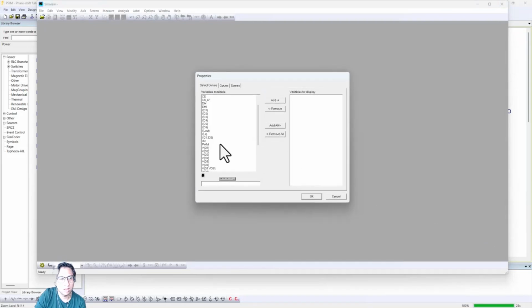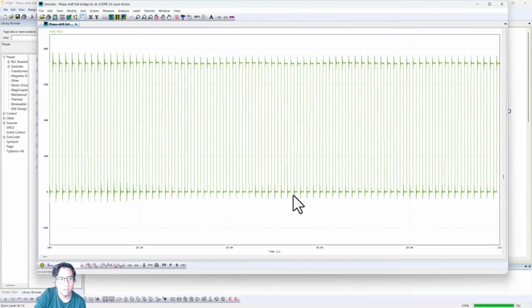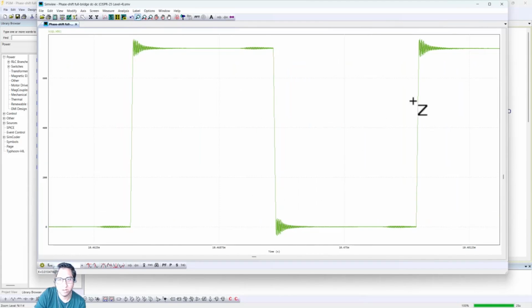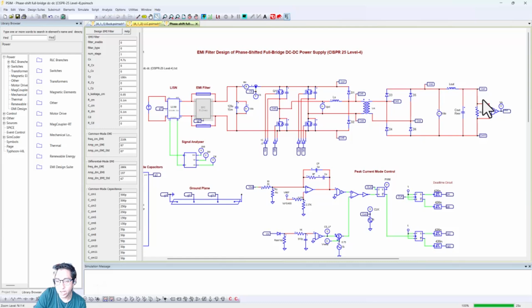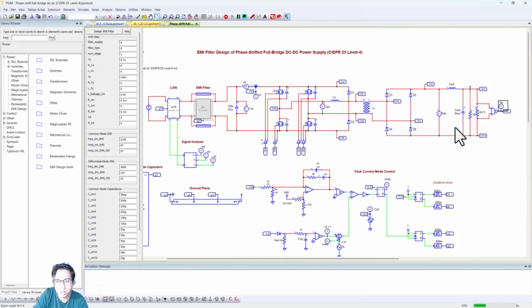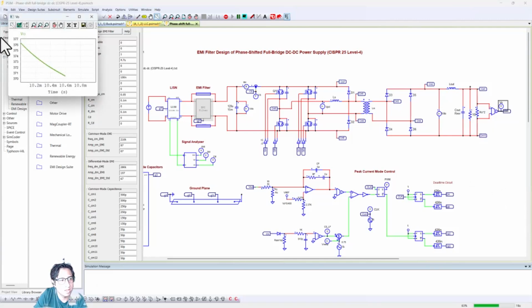It's easy to change values. Let's check the results here. We can see that everything is working, really. The dynamics look a bit different to what we had previously, but we can keep doing this with all of our passives. But again, what we cannot do is place this resistor here and start simulating. PSIM won't detect an error, but things just won't look good, right? Which in this case means that the voltage is just dropping.